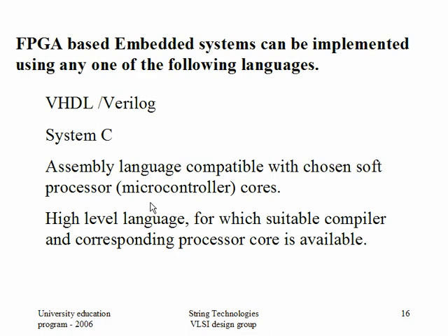You got the point? Now I'll tell you what hardware software co-design is, especially from the FPGA perspective. Imagine I have an FPGA. The FPGA has, let's say, one hard processor, or I may use one soft processor. On top of that I am writing some software. Whenever I write sequential C code or assembly code, we call it pure software. So I am designing some portion of my system in terms of software. In the same FPGA, right beside my processor, maybe hard processor or soft processor, I have logic cells also. I am writing my VHDL code or Verilog code to implement some hardware logic in the logic cells. You see, now I am doing hardware and software together. This is what we call hardware and software co-design.